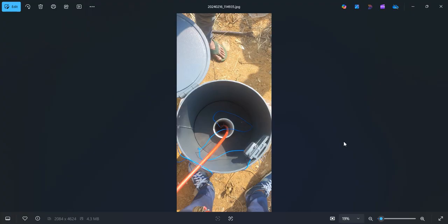But make sure these batteries have more capacity, and they are self discharging, and the battery life is also high, because once you install the seismic station, you may or may not have the time to go check the batteries and all every time. So that would be good if we have batteries with a longer life.